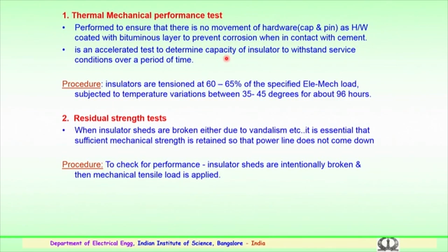So, the equipment in use should not weaken; that is the intention of conducting the thermal mechanical test. This is generally an accelerated or long term test to determine the capacity of any insulator, glass or porcelain, to withstand service conditions over a specified period of time. This specified period of time is based on the standards, the manufacturers and the utilities.